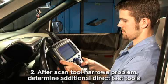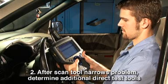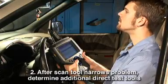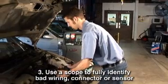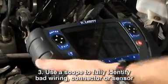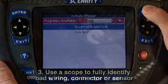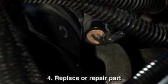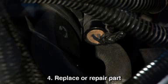He now knows he needs more specific direct test capabilities to test the circuit. This is where the 4-channel scope must be used. 3. The scope is used to do a more in-depth look at the circuit, and can help to specify if the problem is in the wire, the connector, or the sensor. 4. In this case, it was the sensor, so the technician replaces the sensor.